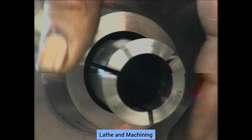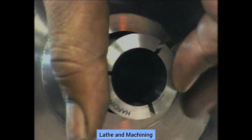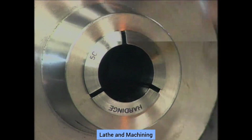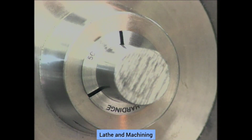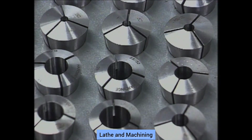Collets, which usually seat in the spindle of the lathe, are hollow cylindrical devices with slots along most of their length. A collet opens under its own spring tension and is closed securely to grip the stock. They hold small diameter round work on center. Chucks and collets come in many types to suit various workpieces.